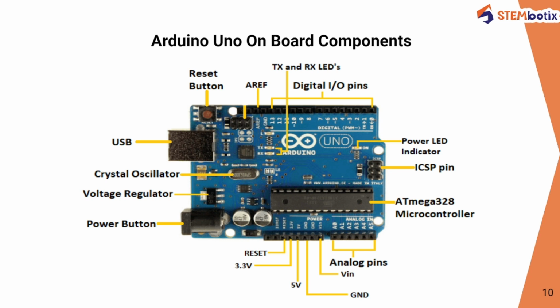The speed of this flashing depends on the baud rate used by the board. According to the baud rate your board is set to, the LED's flashing timing will change. RX flashes during the receiving process. If you are sending data, TX will be turned on, and while it is receiving something, the RX will flash.